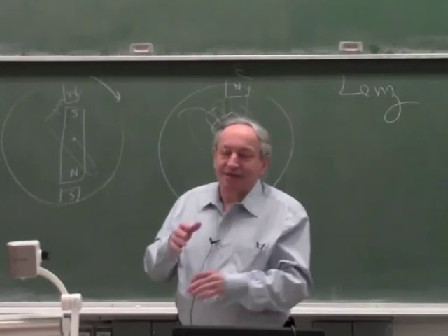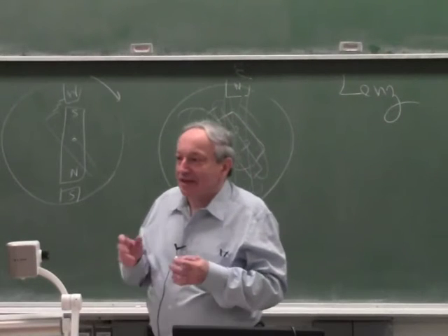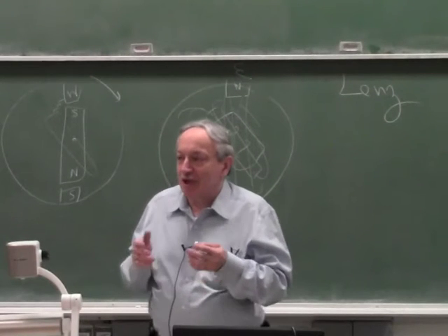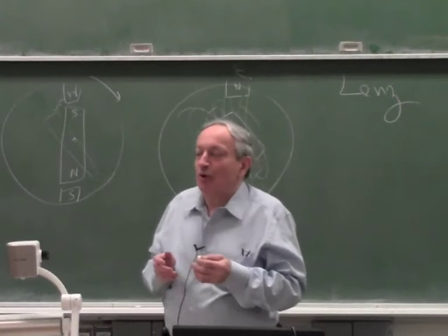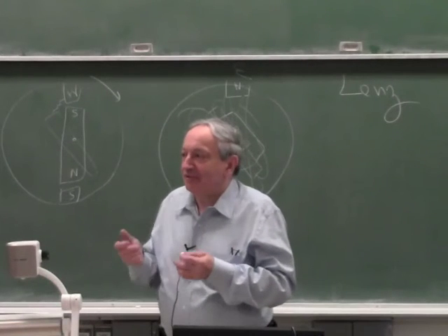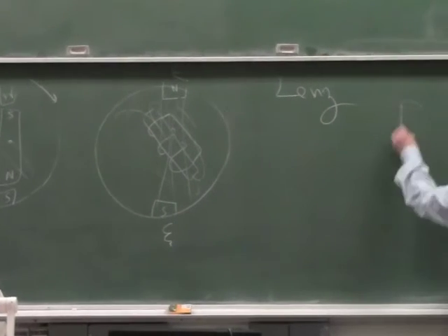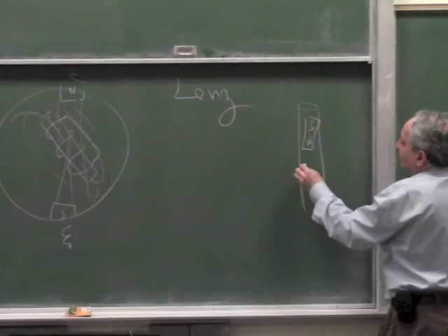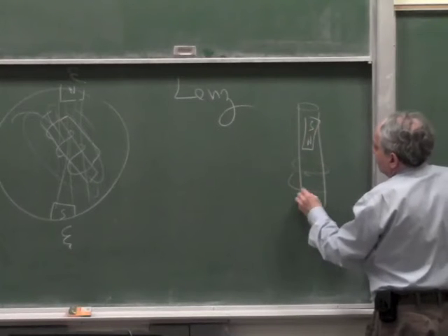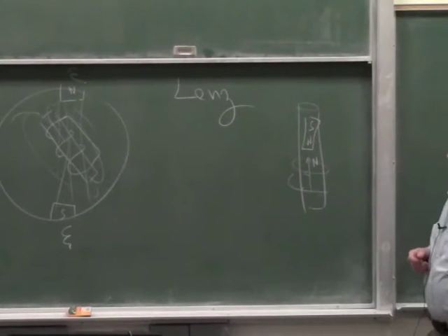Produces opposing. Exactly, because there is something called Lenz's law, which says that any current created by a changing magnetic field will try to oppose this field. It will try to create a field which is opposed to this field. So if you drop a magnet through a copper pipe, there will be currents induced, and these currents will try to form a magnet of opposing polarity.